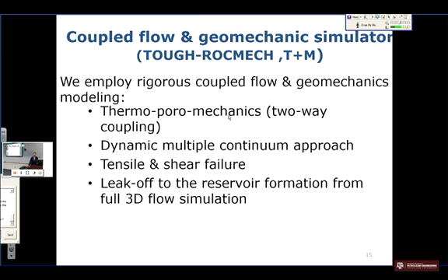It does not affect things significantly. Slowly, once you create the fracture, you start filling it up, and then the volume changes. Then the material changes. If you're saying that this may be introducing an error, it is about an order of magnitude less than the convergence criterion, which is 10 to the minus 5. So initially it's a very small error, but in the process, this is corrected.